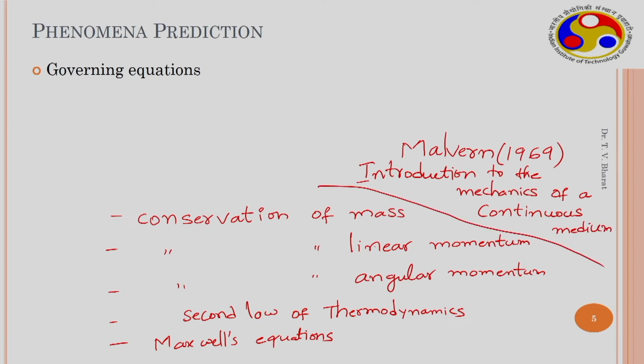Apart from these physical laws, we also require additional equations to solve the problem uniquely. These are material dependent equations. Constitutive equations therefore explain the interdependency of different state variables, such as stress, strain, void ratio, effective stress, etc. The proportionality constants of the constitutive relationships are called material constants that represent the fundamental constituents of the system. Material constants may also depend on the state variables.